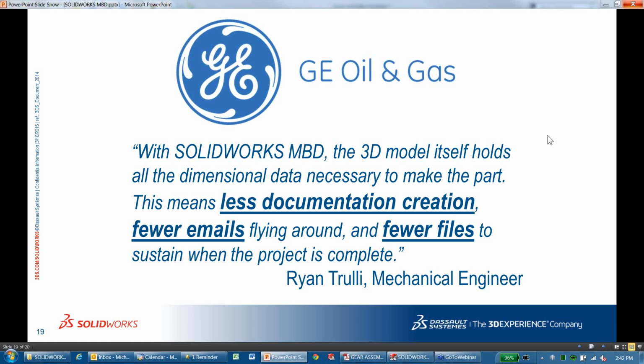It's not so much for the machinist; you're basically just not having to create a file for the machinist with the drawing on it. Typically you would send the SolidWorks file, so you can read it into his CAM software, but you would need to create a drawing with all the dimensional information, the GD&T, so that the machinist knows what the tolerances are and how to machine the part.